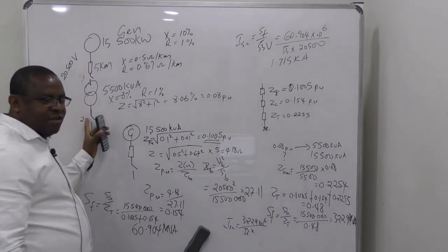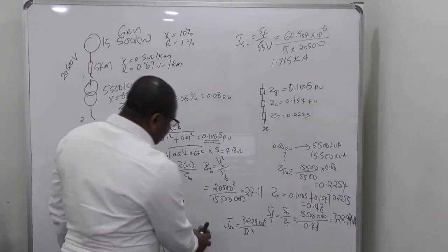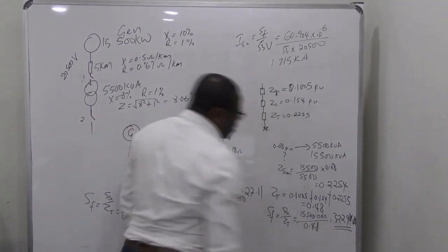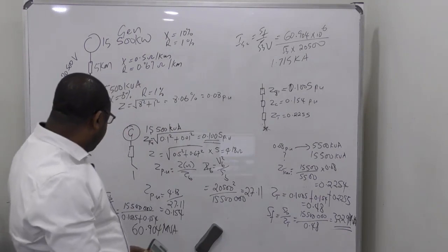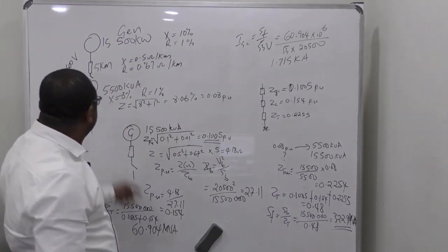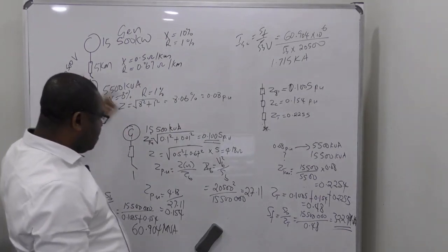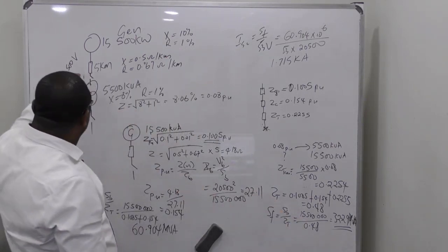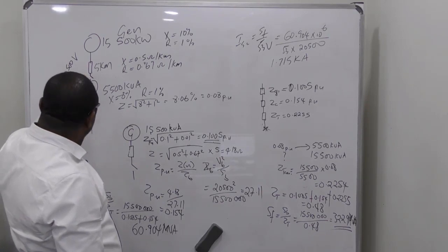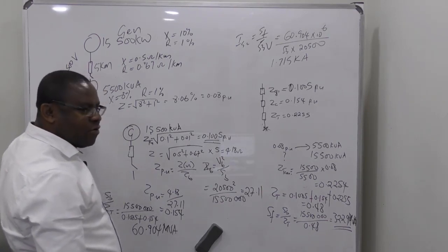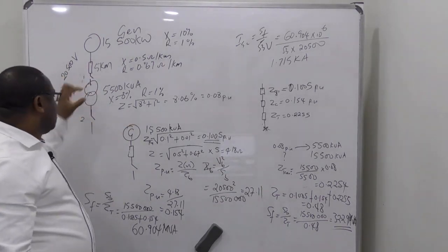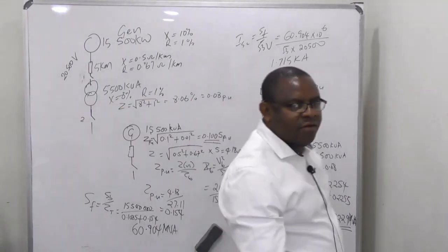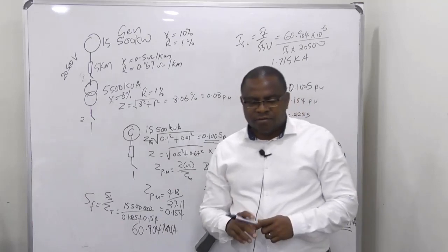But we're not given a voltage here, so you just stop here. This is the rupturing capacity in MVA at this point. You can see that the capacity has decreased from 60 at the earlier point to 32 at this point. Why? Because the transformer being there restricts and reduces the fault level.